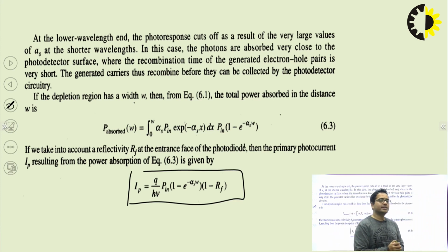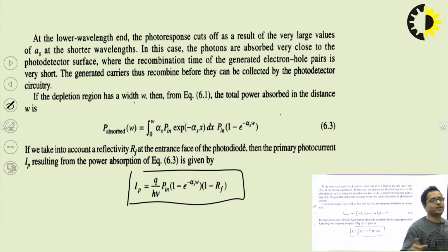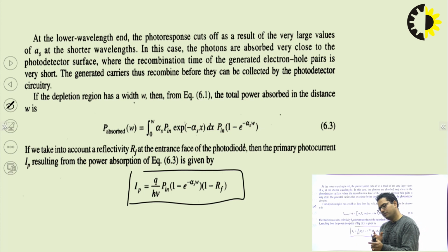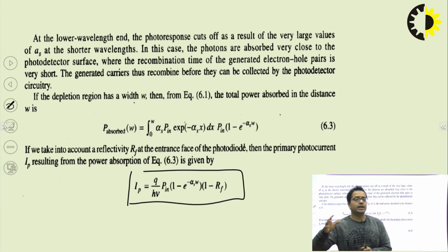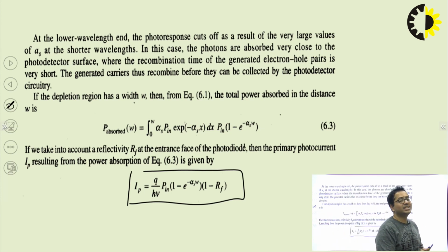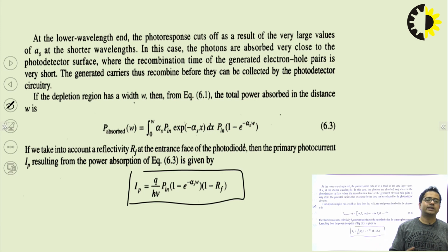This increased number of electron-hole pairs is going to be swept apart with the help of the attraction force, that is, attracting the hole towards the n terminal and the electron towards the p terminal. As a result, they will start flowing, a closed loop will be formed, and the electric current will start flowing. Now, this was the very basic concept associated with the photodetector.